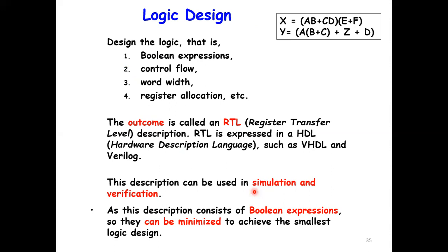Everything is specified in the logical design. The outcome is called RTL, register transfer level description. RTL is expressed in VHDL. When you write programs in VHDL or Verilog, and VHDL is what is taught, a report is generated when you synthesize. Have you ever seen it? That report is basically RTL. It is called the RTL report, register transfer level description or report.